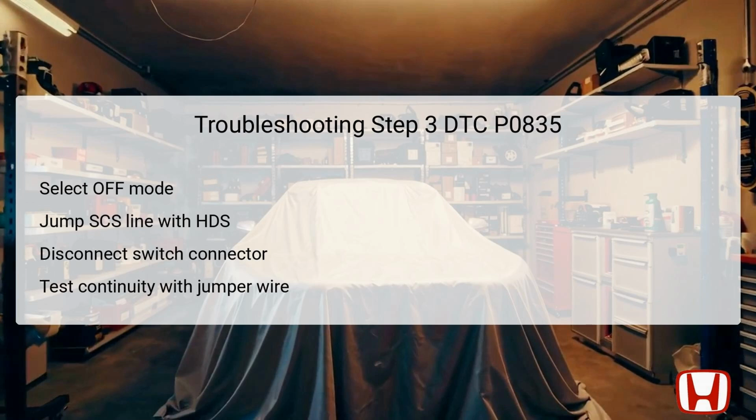status. The technician then connects terminals A and B with a jumper wire to facilitate a continuity test. Terminal A corresponds to the 3P connector number 1, black, while terminal B corresponds to the 3P connector number 2, LT blue. Once these terminals are connected, the technician checks the status of the clutch pedal position switch B in the data list using the HDS. If open is indicated, next steps will be taken to ensure the wiring is intact. If not, it suggests that the switch may require replacement.